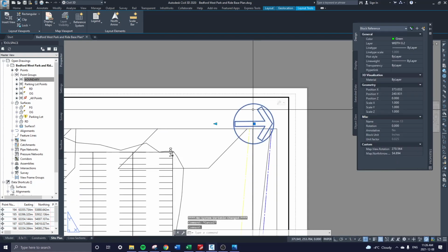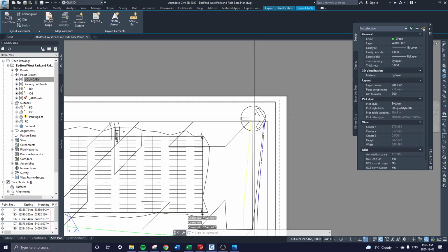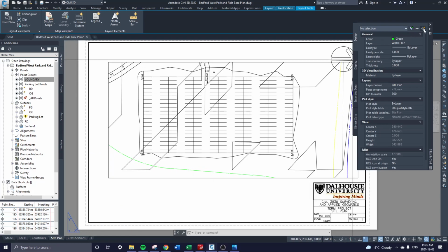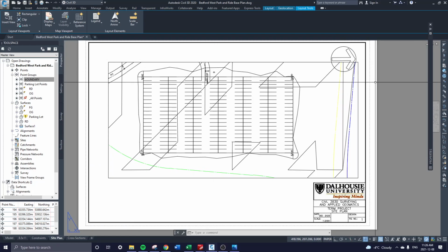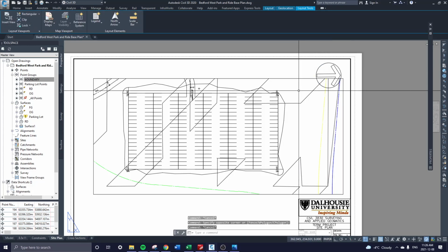And then what you should probably do is explode it. North arrows and scale bars on drawings are very, very prone to glitching out your AutoCAD and causing errors and maybe even crashes. So just try to explode it when you can, but that should orient nice for you.